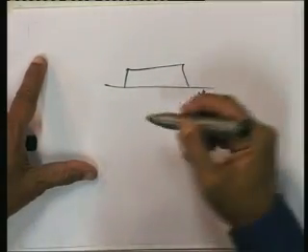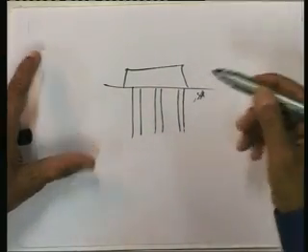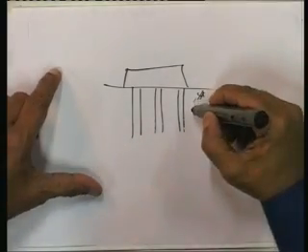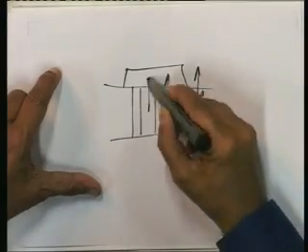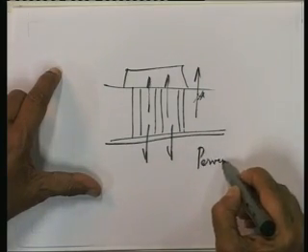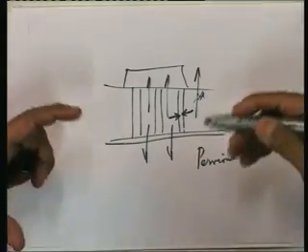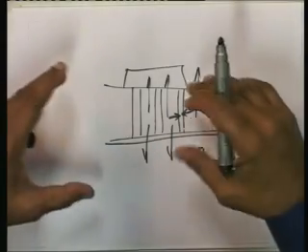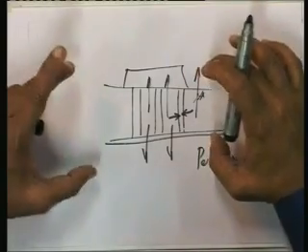In order to facilitate this consolidation, if you install what are known as sand drains, we had discussed this also in the past lecture, then the flow of water takes place due to excess hydrostatic pressure not only in the upward and the downward direction if the downward layer is also pervious, but it also takes place radially. In view of this, there is a tremendous amount of acceleration in the rate at which the consolidation process takes place. Now, how does one estimate the total consolidation that takes place when there are 2 components to it?